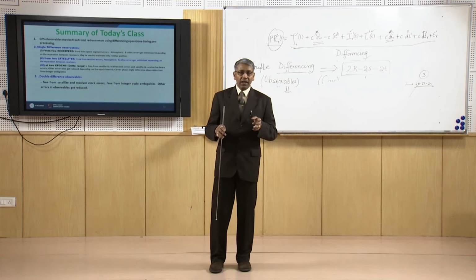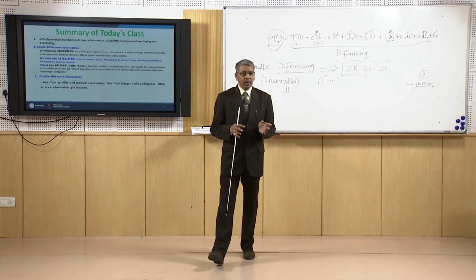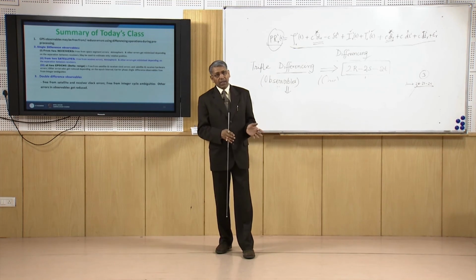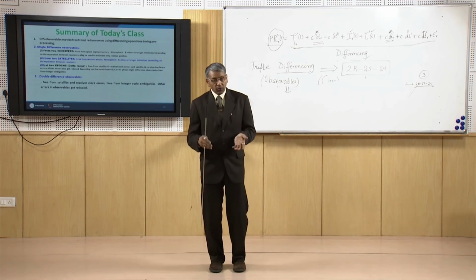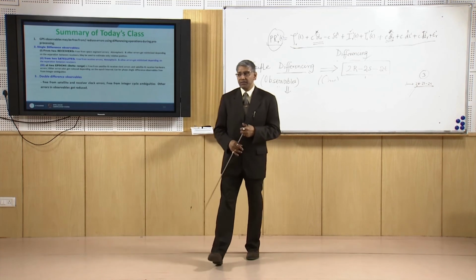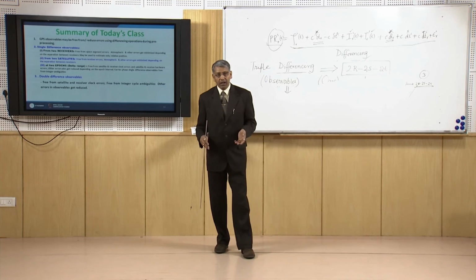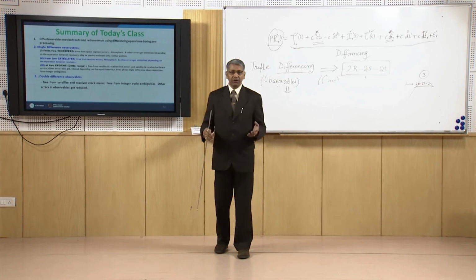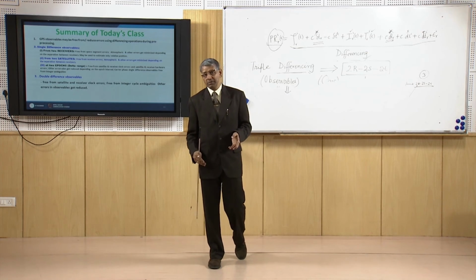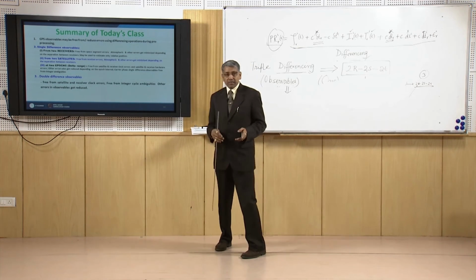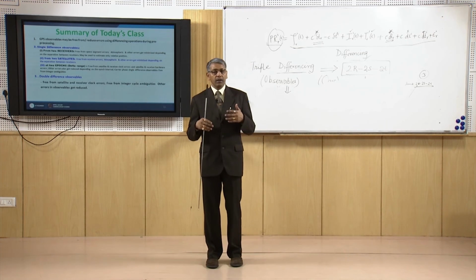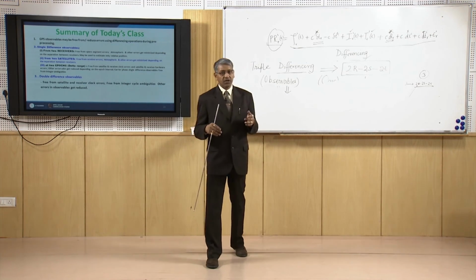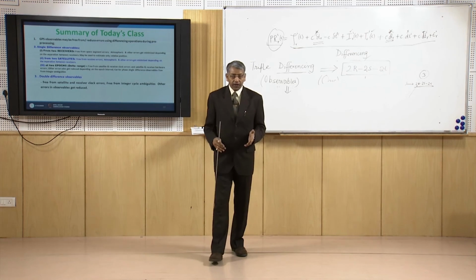That means by taking the differences of GPS observables, we may generate new types of observables, and there are three ways we can generate them: single difference observables, double difference observables, and triple difference observables. Of these, the double difference observables are most useful for GPS data positioning.